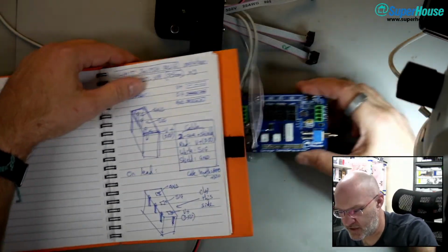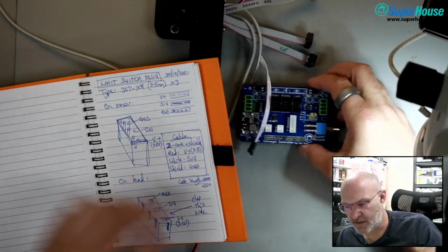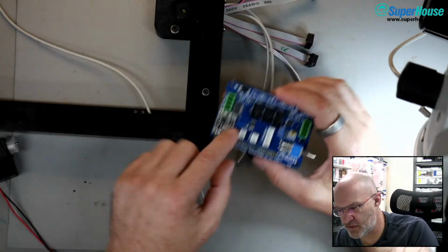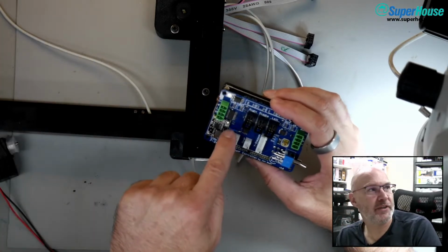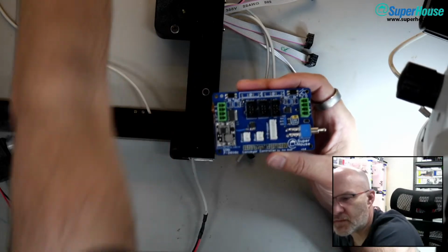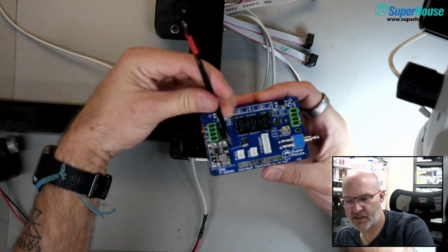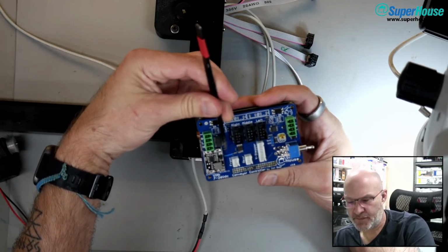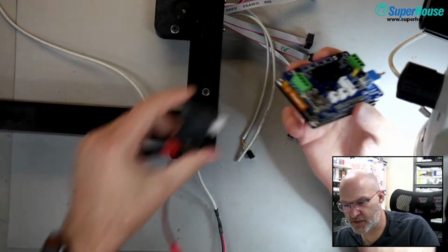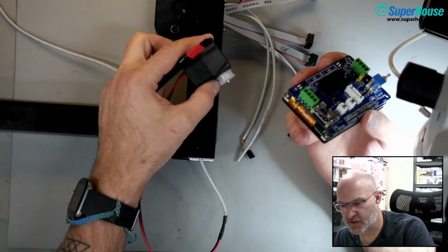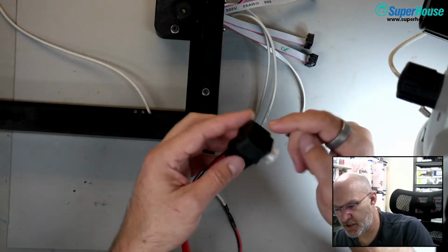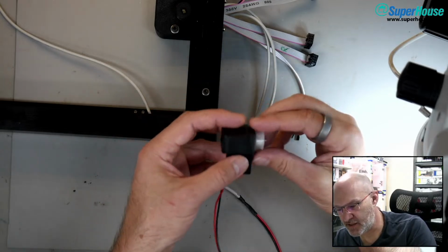I need to change this connector. So I do need to do a revision of this PCB. One reason is, if you look very carefully just down here, can you see it? Slightly out of focus. Just down here, there is a bodge wire. And that is because I changed from running these motors at 5 volts to running at 12 volts. And these are just N20 gear motors. It's inside that 3D printed housing.